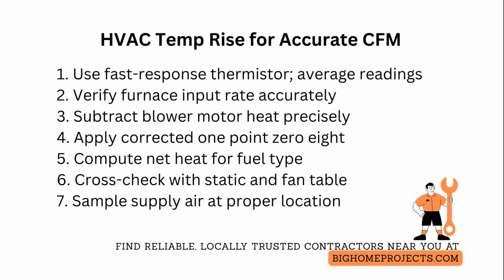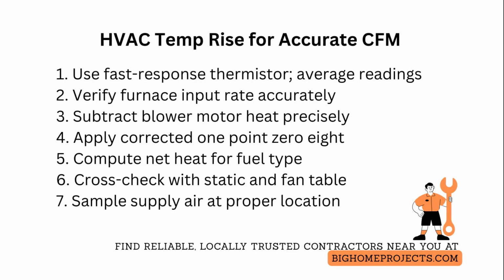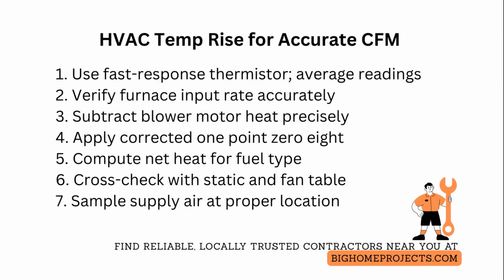Cross-check the result with external static pressure and the blower fan table. If the table predicted cubic feet per minute and the temperature rise cubic feet per minute disagree by more than 10%, re-verify readings before changing tap speeds.